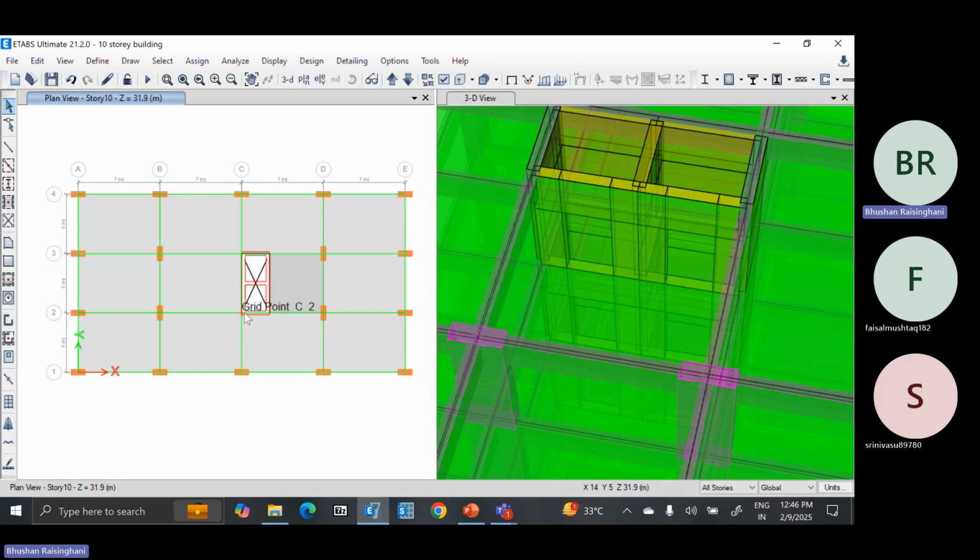But on the top floor, only on the top floor where the loading I have to apply, I will delete this opening. So I want it to act as a slab, so I can apply 15 kilonewton per meter square in this particular area only. Okay. So for that also, I will have to divide the slab in this particular joint. So either you can model it separately or you can then tweak accordingly.